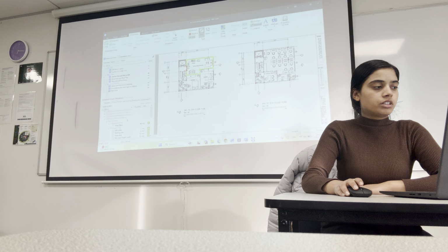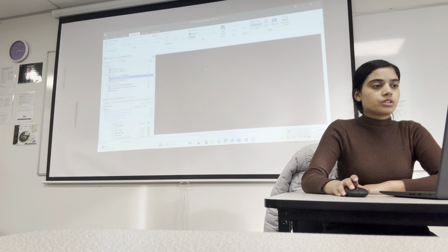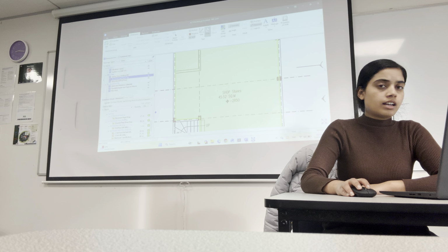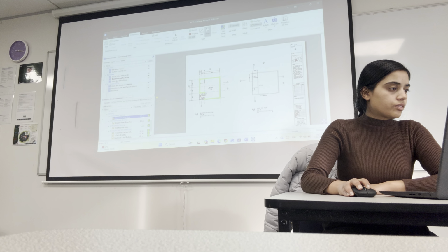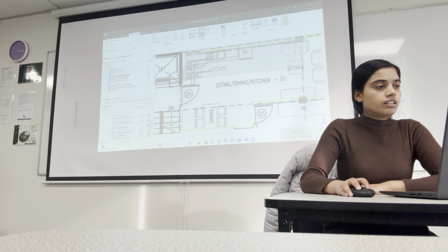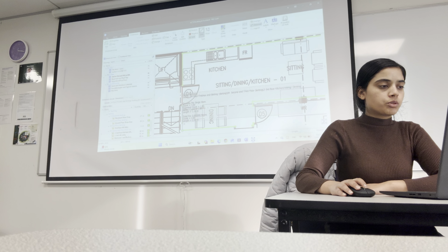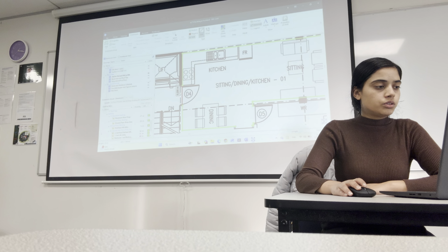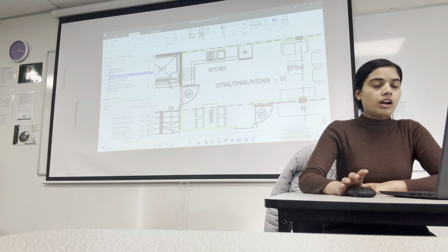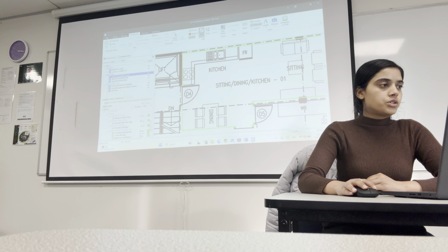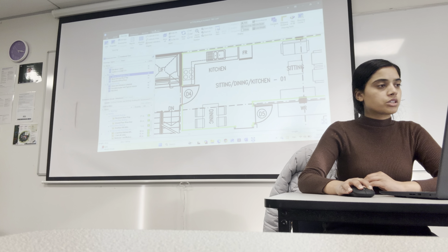The most important thing is I measure the wall as area, so I do it from the point mode. And for the skirting, I measure the wall in meter. I measure wall to wall, but I deducted the size of the door because I don't need to worry about the skirting in the door. After completing all the dimensional groups and the drawing calibration, I will move towards the workbook.